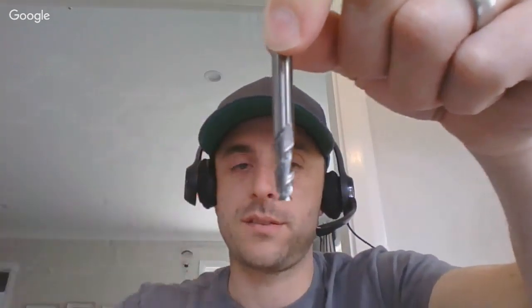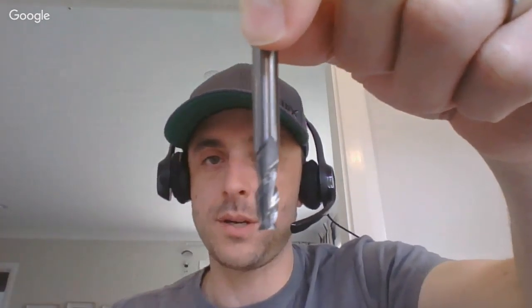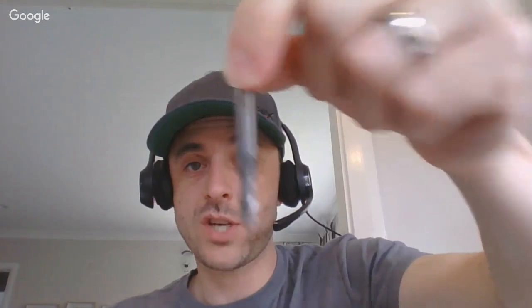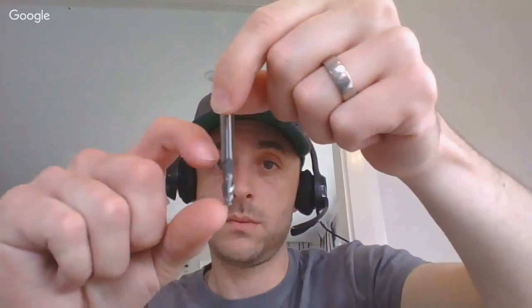I think that's pretty fair. If you're cutting 18 mil ply, then you're obviously going to need something that's got enough flute to get all the way to the bottom. Even if you're only taking 4 to 6 mil step downs, you still need enough flute length to get to the bottom. So this one's not going to do. That's a 16 mil flute length. I'm pretty sure we don't even do this anymore. We've changed this now to a 20 mil flute length because so many people are cutting 18 mil ply. So I tend to agree with Brett.